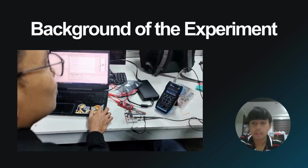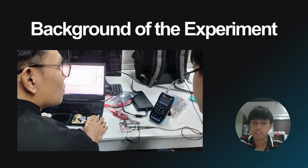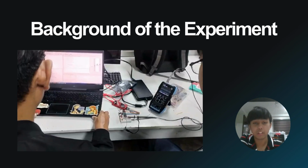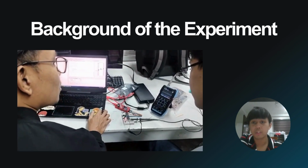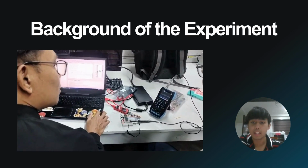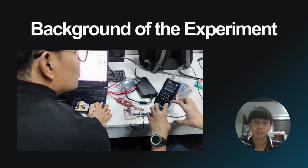multitasking. Timer 0 can be configured to generate interrupts, which trigger a dedicated interrupt service routine, or ISR, when the timer overflows. The main program can continue its execution, and when the ISR is invoked, it will perform the necessary actions to signal the completion of the delay. Interrupt-based delays are suitable for applications with multitasking functions.